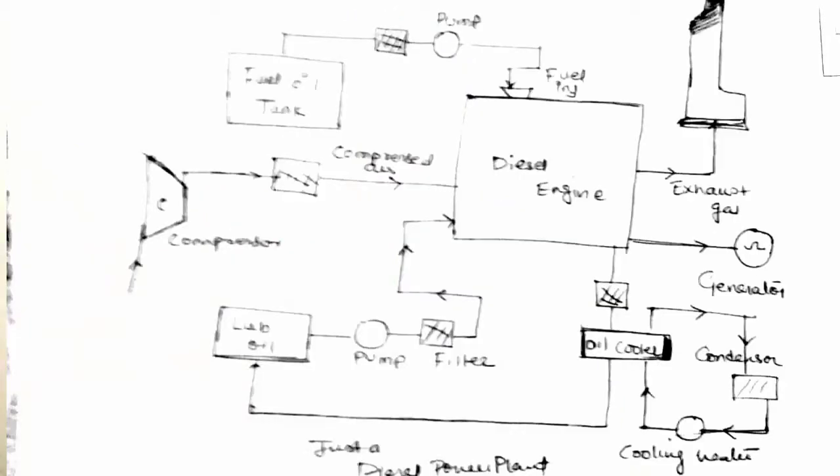So to reduce the temperature of the oil which is being circulated in the engine, that is bringing the hot oil out, absorbing the heat from the engine, and again you are cooling it and supplying it back, so that you are getting the cool oil and again removing the heat out. So again, there is an air compressor which will be used to increase the pressure of the air before it is supplied to the engine for the combustion purpose. So again, the need of the compressor was to supply the high compressed air. So these were the different components of a diesel power plant.